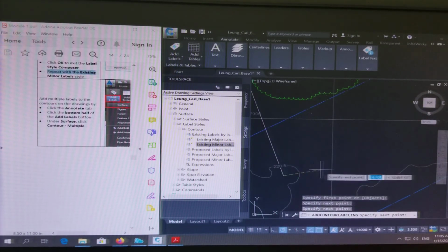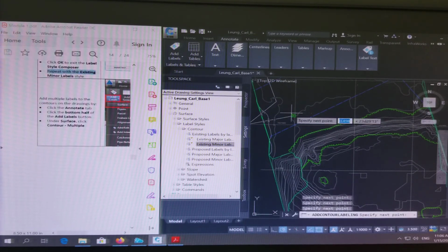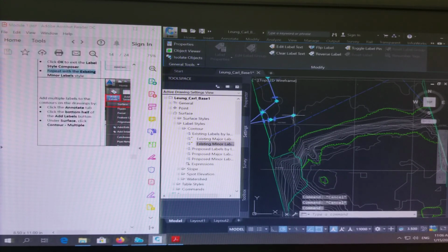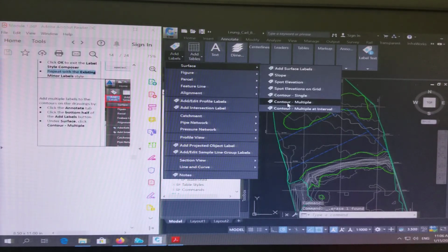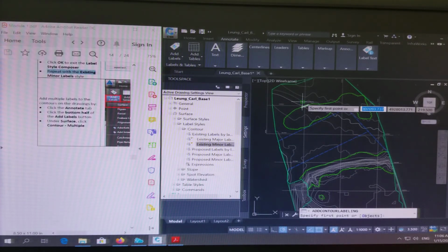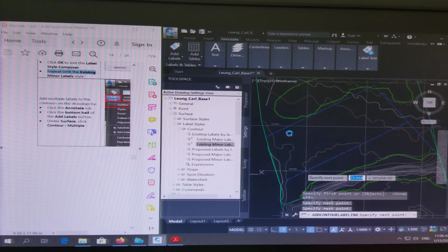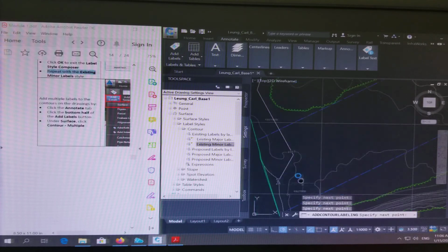Now, where do you place them? Just whatever. Just place them in a good way, don't do like I did. Let me delete this. Maybe for doing this, it's better if you turn off your OSNAP. How do you turn off your OSNAP quickly? F3. Just F3. It might be Fn F3 if you're using a laptop, but here just F3. It turns off. Then you're gonna go here, here, here, here. Maybe I don't want to cross again there, so I'll go here, here.